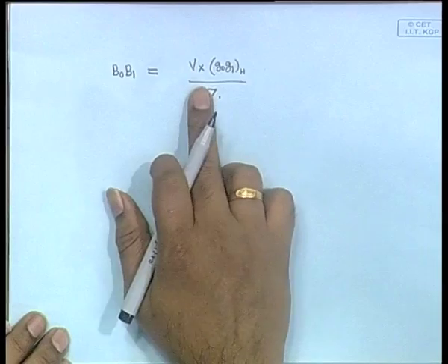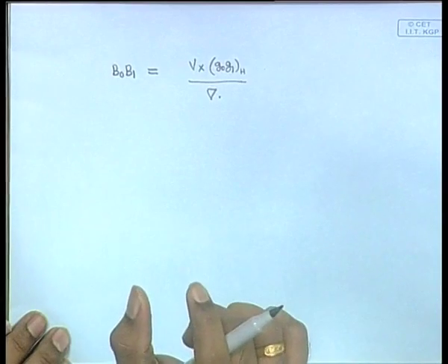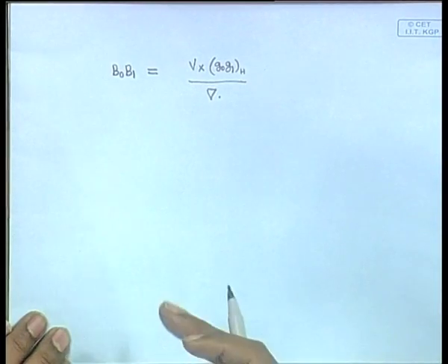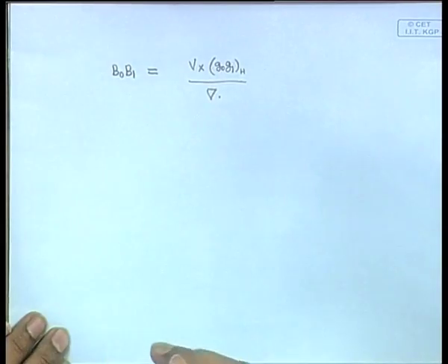So, that is what this is: B0B1 of the ship is given by v into g0g1 of that small wedge, the distance through which the center of gravity of the wedge shifts (center of gravity or center of buoyancy, it is the same, I am not differentiating here), divided by delta of the ship. H means horizontal. Remember I told you that the whole movement of B I have split into a horizontal plus a vertical.